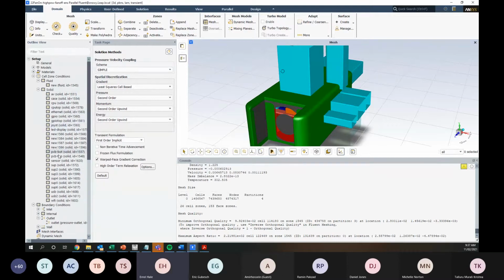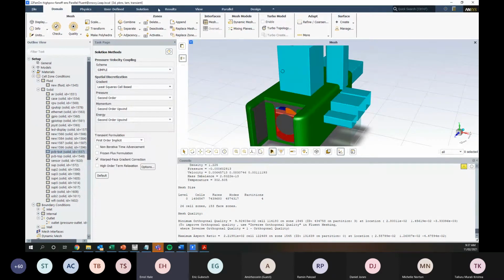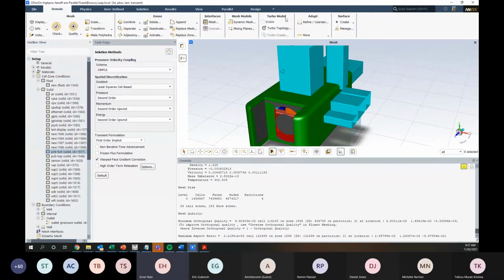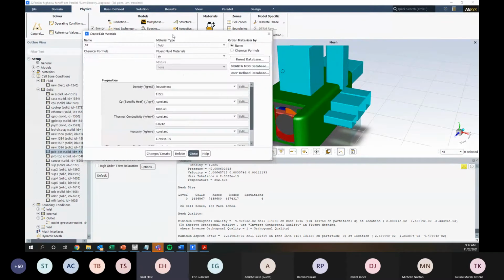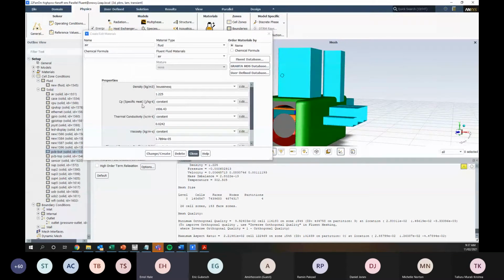And you can see, okay, so let's open another one. PCBs, so material name PCB. So I've spelled it that way because it has orthotropic material properties. And that is, it is much more conductive in the in plane than it is in the through plane.